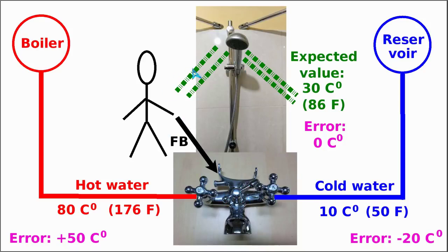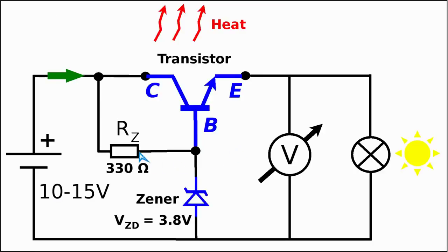Such type of negative feedback loops are used in almost every switch mode or linear power supply, and this is why today I have taken the time to explain the individual components when it comes to the feedback loop. So now you should be familiar with the input, with the output, how we are calculating this error, and based on the error, how the controller is sending the feedback signal to our control element. So after this short lecture on loop control theory, we are now back with the original schematics, and let us now try to identify what the individual components are when it comes to loop control theory.